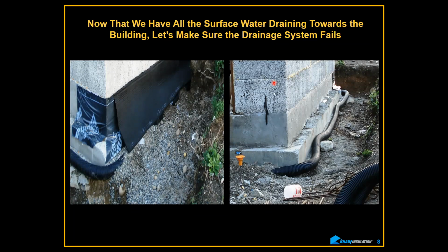So let's talk about this first. How's the water going to get uphill here? We don't know how that's going to work very well. There's no protection on here. There's no waterproofing, no water repellent, no damp proofing on here. This has not been cleaned off to accept it. What happens is you get something like this on the left-hand side. Water gets in under here. It's very poorly done. You've got a big open gap here.